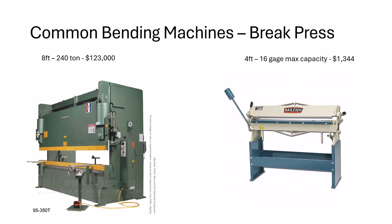Real quick, the common machines for this type of bending are brake presses, what they're called. Big variety. There's these big industrial ones, the 8 foot long, 240 tons, $100,000, and then you can even go down to a hand-operated one right here. It's only 4 feet, 16 gauge max capacity, $1,000, and you're going to have brake presses anywhere in between them.